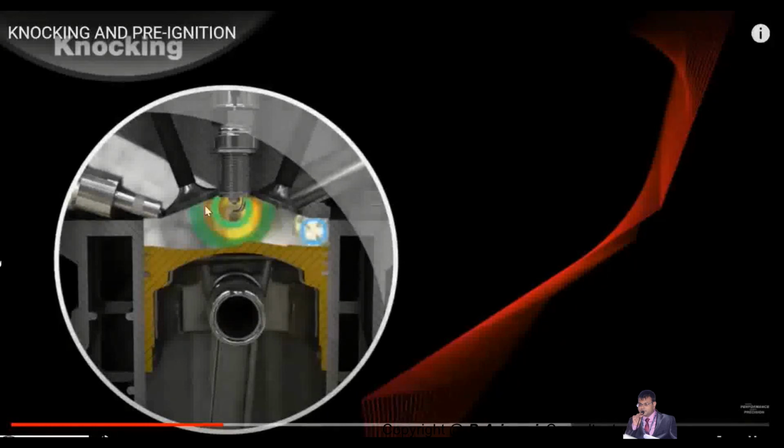And here the spark will not happen, but the ignition will happen. That ignition will create a flame, will create a combustion. Basically, when you have the combustion, it is nothing but a flame. It propagates from the top region to the down region. Already there is a combustion or flame happening from the bottom to the top. So these two flames will collide, and you get a sound, the knocking sound.